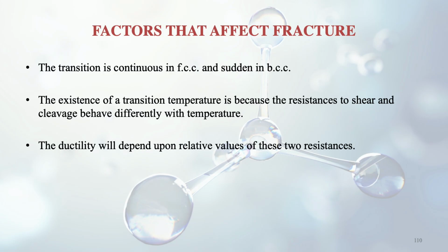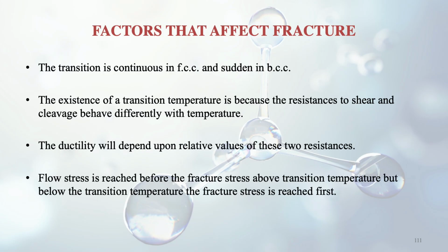Ductility will depend upon the relative values of these two resistances: shear and cleavage fracture resistance. Flow stress is reached before the fracture stress above the transition temperature, but below the transition temperature the fracture stress is reached first. So above the transition temperature, the flow stress is reached first, so fracture will not take place. But below the transition temperature, the fracture stress is reached first, so fracture will take place and there will be no plastic effect. It will be clearer from the figure given here.